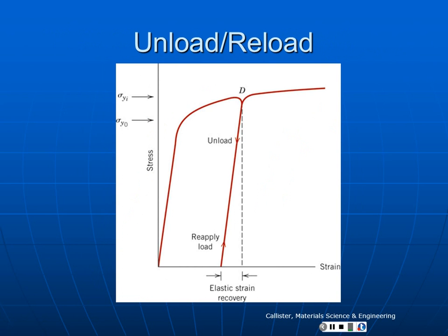Now, when you're running a tensile test, and it's possible to do this in the lab, although not a trivial exercise with the way you guys are set up right now, you can start a test and you can stretch the material. You could pause the test and unload. And if you unloaded, the slope here would be the same as the original slope, so that's the same modulus. You get your elastic recovery here. And if you then reload, you'll come back up this line, and then it'll just pick up again where it left off.